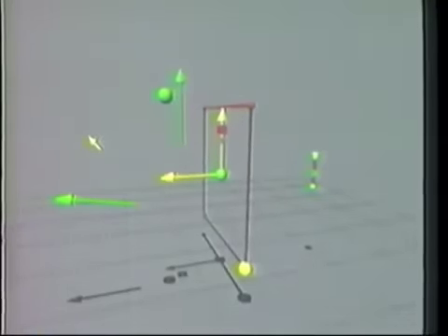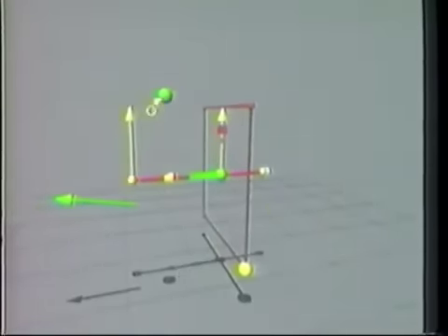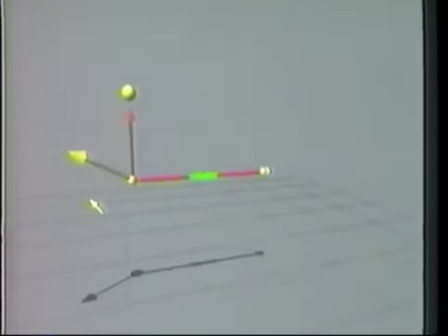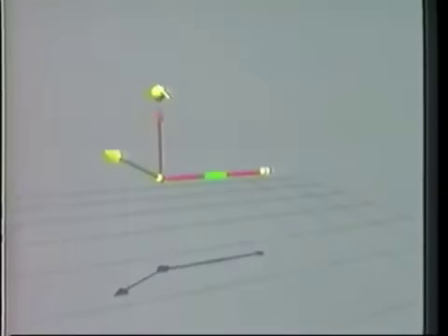We start off with a collection of widget primitives and link them together so that they behave like handles. First, we use a length widget to represent the axis of deformation. We link this to the normal to a plane. The handle used to taper consists of a point and a ray, and is constrained to be perpendicular to the axis of deformation. The bend handle, represented by a ray, is linked to one end of the axis of deformation, but has no orientation constraints. Now we undraw the plane to make the widget less cluttered and easier to understand. We see that the handles now have limited degrees of freedom.